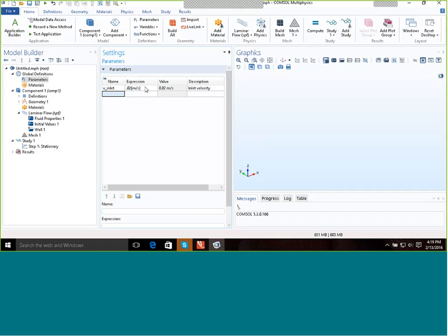If I tried to change it manually, so if I put in the number 0.02 meters per second into my model directly, and it might be in there in 3 different locations, and now I want to change it to some other value, 0.05 meters per second, I might not be able to find all those locations, and I might get totally messed up. I might just change 2 out of the 3 locations, and the model will get messed up. So it's good practice to start off with a table of parameters.